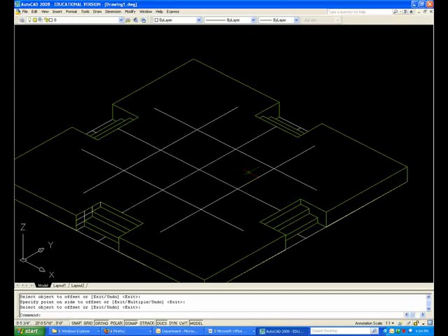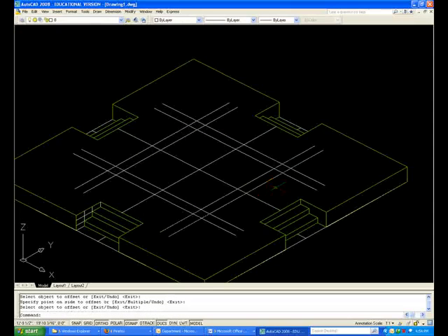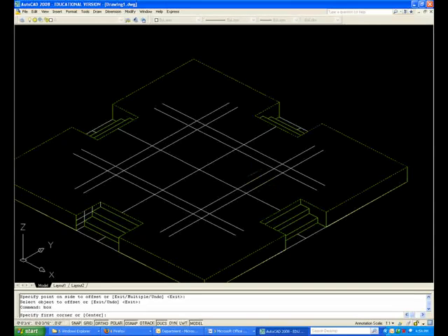Now for the sake of argument, I'm also going to create an offset of 12 inches from there, and I'll be using that to locate my roof later on in this process. But nonetheless, let's go ahead and create the walls. We want to create basically a box. And that box, if you look at the notes, is inscribed within a 15-foot by 9 by 9 box.